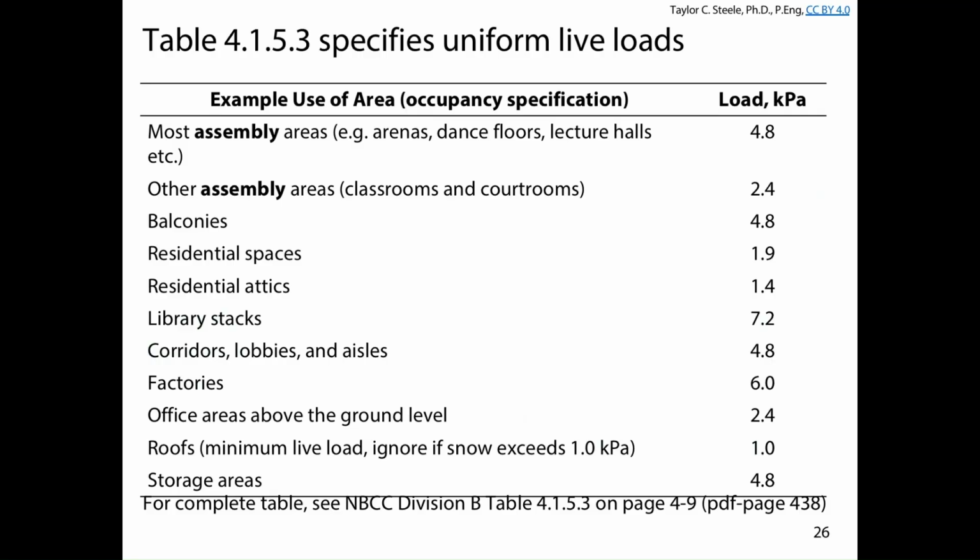We're going to look at a live load for the office area of 2.4 kPa. And we're going to keep these separate. We cannot reduce roof live loads. We can reduce office live loads. And so we'll come back to that when we do those kinds of calculations.